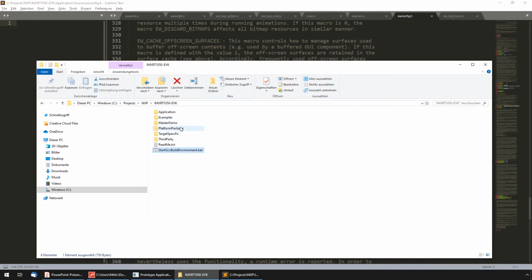So inside these, going back, application project, for example MDK ARM, there are the proper project files. There's also a readme.txt, which is essential to read. Something that customers sometimes ask us is why there are these so-called EW post-process commands. This one applies to Keil MDK as well as for IAR. These are used in order to manipulate and adapt the project, so the Keil project or the IAR project, according to your current GUI project that you have defined with Embedded Wizard.